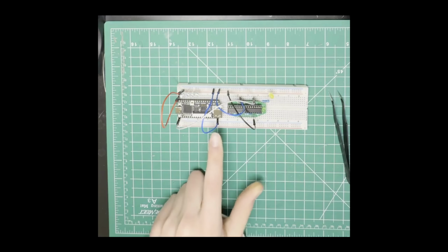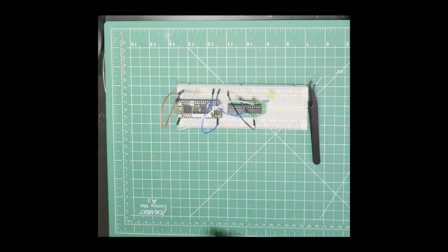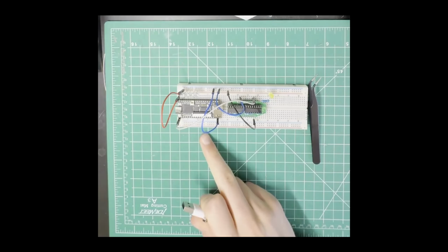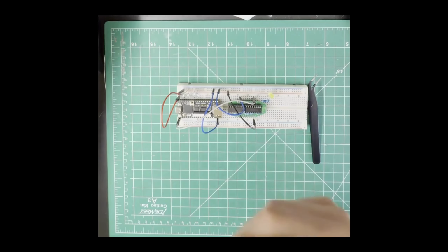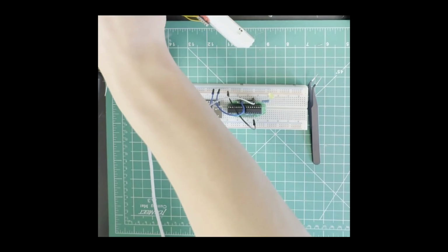Now, this is an 8-bit version, since it's on an FPGA, and so I just have to change one parameter in my program to make it as many bits as I want. In theory, I can make it 128 bits, since this is a Tang Nano 20K, and this has 20,000 programmable LUTs. And so this allows for a lot of freedom.